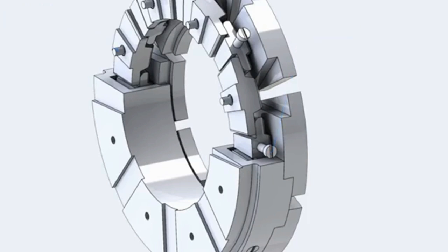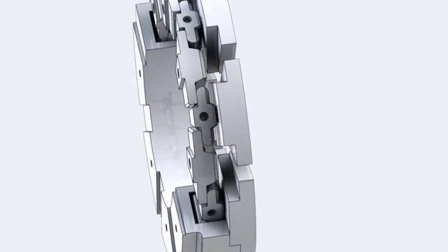The load transmitted by the thrust runner to a single pad causes the pad to press on the upper leveling plate right behind it. Each of the upper leveling plates in turn is supported by one edge of two lower leveling plates. The other edges of the lower leveling plates take part in supporting the adjacent upper leveling plate on either side. As a result of this arrangement, any excess of thrust load on a single pad is immediately shared through the leveling plates, so that all bearing pads will automatically receive equal loading.